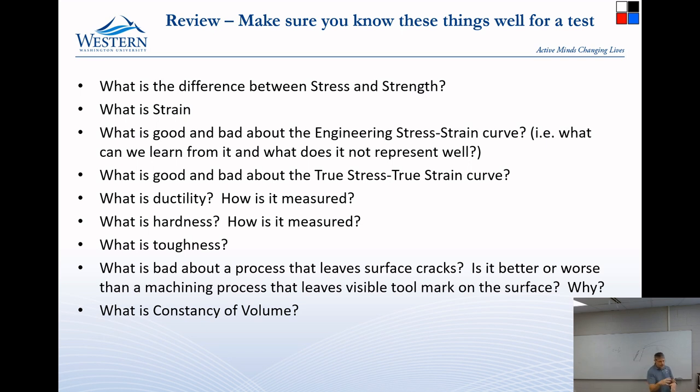When it refreezes to the surface, because it is a liquid, the surface tension draws it into a little sphere. So it draws into a sphere and refreezes to the surface. Then the next little spark happens and another little sphere appears right next to it as it's machining material away. So in between two spheres is a very sharp crack. And that crack can then propagate through the material if you oscillate the material.